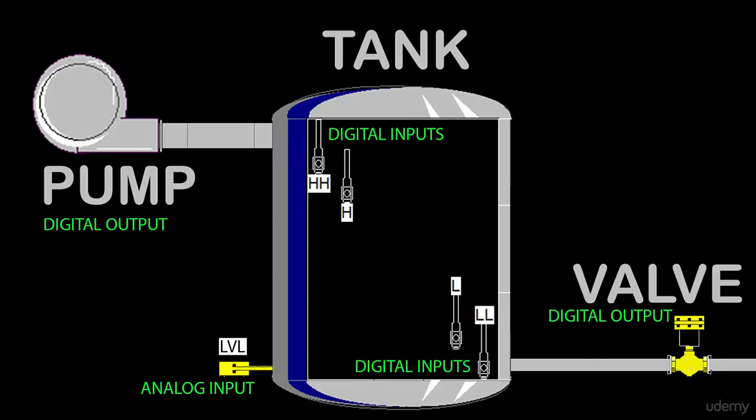It's going to trigger an alarm. It's going to warn the operator, hey, we've got a problem. And the system is going to take steps to protect itself so that nothing goes wrong, if at all possible, to prevent any type of catastrophe. So in process control, low and high are your control set points. Low low and high high are your alarm or emergency set points.